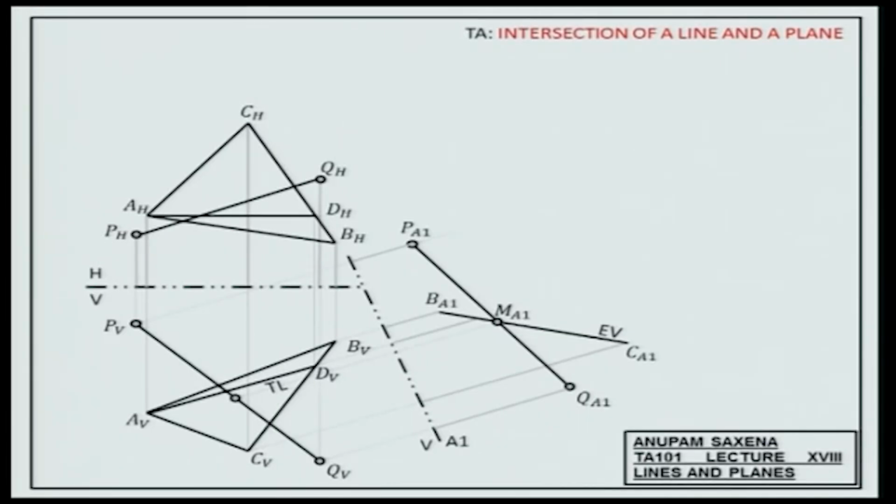That's MV, and now you realize that the point also is within the plane. Take it up. Again, it has to lie on the line. MH. Again, it's within the plane. So if you see these signs, you know that the line and the plane, they are intersecting. Otherwise, they are not. Okay?